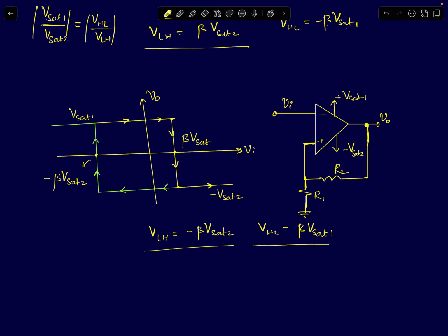Previous examples in the last lecture, for asymmetric threshold voltages, there was a unique value of beta and Vref. Okay. Similarly, there was a unique value of beta 1 and beta 2, which was satisfying those conditions. Here you will not have that. Okay, because there are 3 unknowns and 2 equations, so you won't have that, but you can still get close to the desired values. Okay, there will be some values of VSAT1 and VSAT2, which will give you the desired threshold voltages.